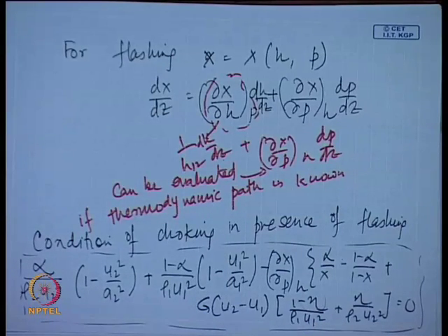This is a problem, because eta also we are not very confident how we are going to define it. Usually from thermodynamic analysis, that is quite an elaborate analysis, probably I will not be going through this, but from that particular analysis people have found out that eta equals half. Usually it is shared half and half by the two phases, but that comes under certain specific assumptions from thermodynamic analysis for isentropic conditions only. For other conditions, it is very difficult to derive eta. Under isentropic conditions for change of phase, we find eta equals half.